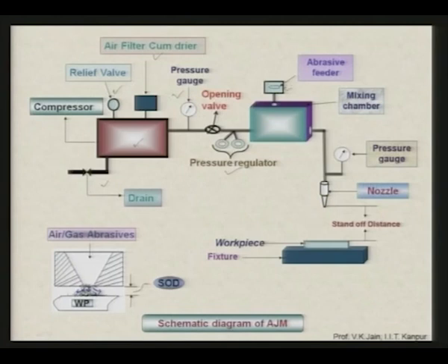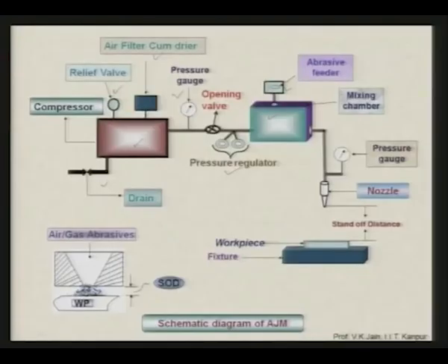With the help of the abrasive feeder, you supply the abrasive particles, and inside this there is a mixing chamber itself, where air and abrasive particles mix together, and the mixture of the air and abrasive particles comes out. You can see here there is a pressure gauge with the help of which you can measure at what pressure the air and abrasive particle jet is coming out.